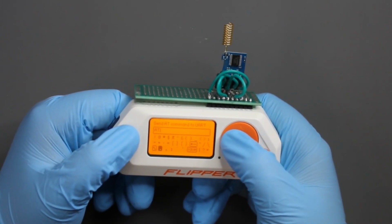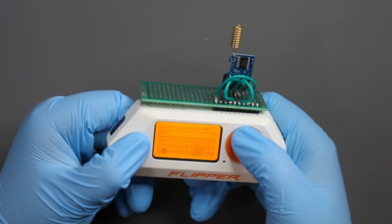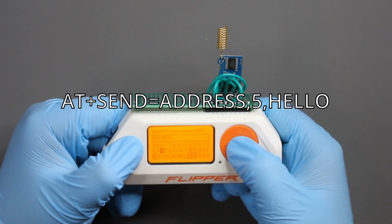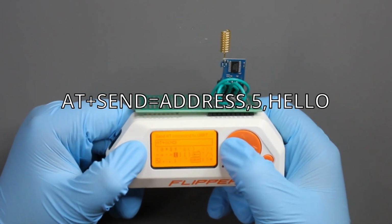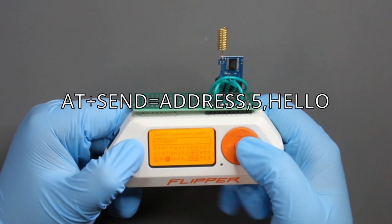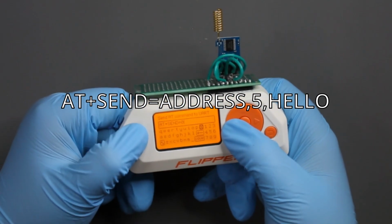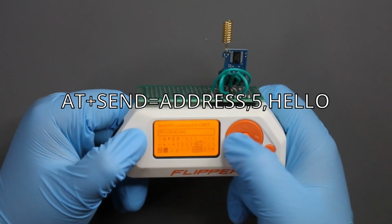So AT plus SEND in all caps, SEND, and then equals, and then put in whatever address showed up on the other command we did earlier. So if it's 0, just type in 0, and if you set a new address, just type in that new address. And we're just going to do a simple hello.